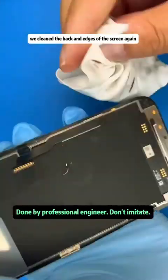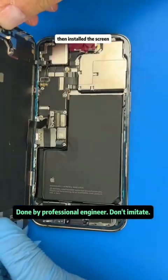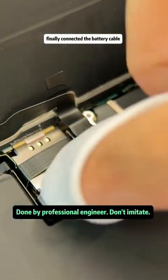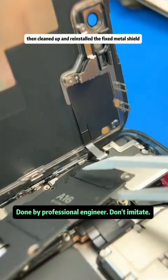We cleaned the back and edges of the screen again, then installed the screen, connected the screen sensor flex cables, display touch cables, finally connected the battery cable, then cleaned up and reinstalled the fixed metal shield.